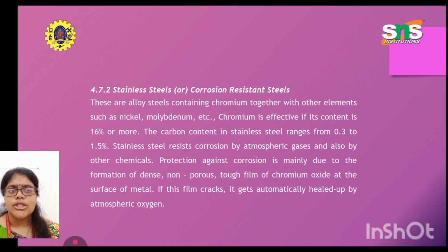Stainless steel resists corrosion by atmospheric gases and also by other chemicals. Protection against corrosion is mainly due to the formation of a dense, non-porous, tough film of chromium oxide at the surface of the metal. If this film cracks, it gets automatically healed up by atmospheric oxygen.